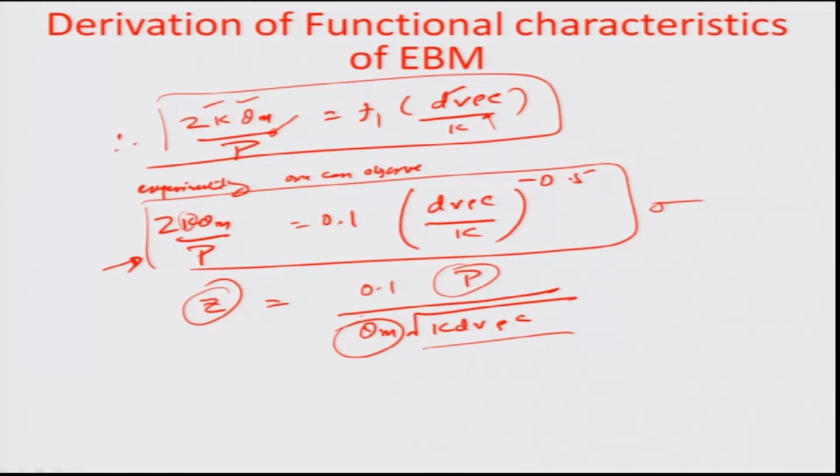So, from the two empirical relationships, you can already observe the power of this technique, that we could arrive at an actual formulation using a non-dimensional analysis, where all these different parameters, the velocity, the volume heat capacity, the conductivity of the material, the beam diameter, the depth Z, the melting temperature itself theta m, and power could all be correlated to arrive at some ballpark relationship which would be more accurate in processes related to e-beam machining. Let us just look at the same experiment that we had conducted earlier numerically and arrived at some velocity.